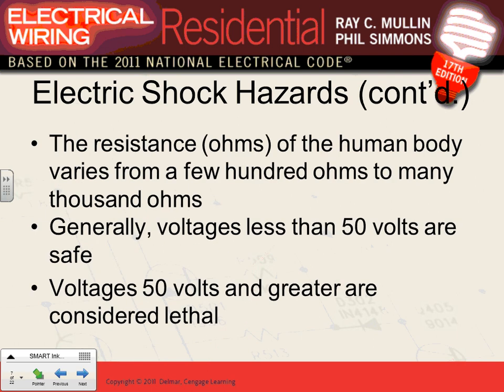You guys know that. So the rule of thumb, not the rule of thumb, the code: anything 50 volts and greater is considered lethal, though you can get lethal at any voltage. But typically in the code, anything 50 volts or higher, we ground the system and consider it lethal voltage. So 24 volts is not lethal voltage, though it could hurt. The lethal threshold usually stands at 50 volts or higher. It's also based on amps, but in order for the amps to move, you need pressure to push the amps.